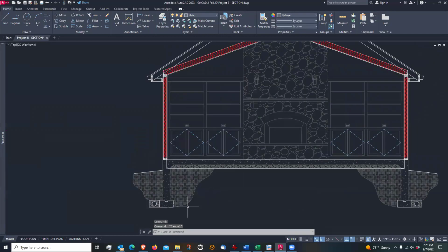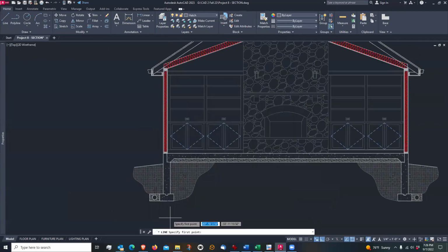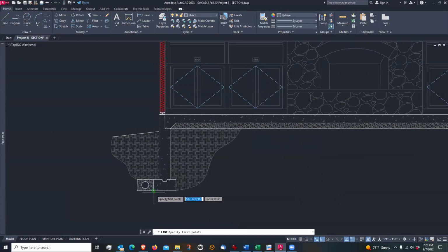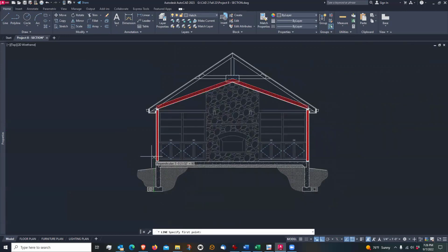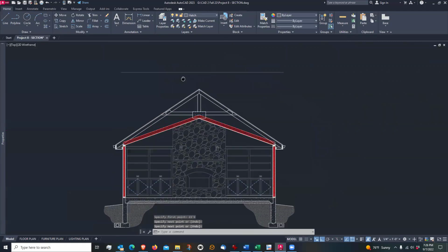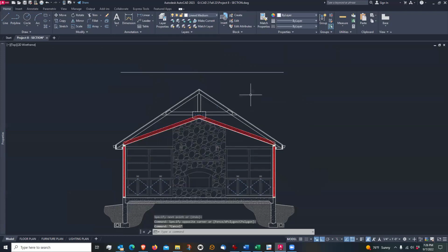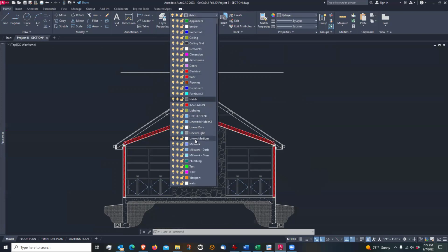So we could do it a couple ways. We could offset that little line 23 foot 6, but I'm kind of in an O tracking mood. So I'm going to O track up 23 feet 6 inches. There it is. And so that's going to mark the top of our chimney. And let me put that also on the line weight medium layer. And also let me set, I'm on the hatch layer by default here. Let me go back onto my line weight medium layer.